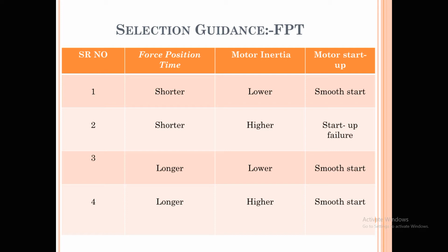If your inertia is lesser, and if your inertia is higher and you are selecting the shorter value, it may be possible a startup failure is happening. In the other condition, if your force position time is longer and your inertia is less, the motor will start smoothly, but it will be a slow start, slow startup.